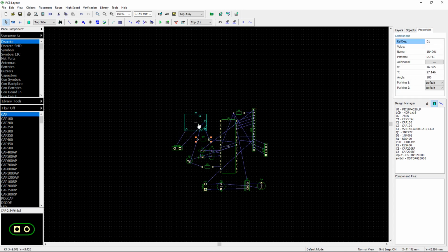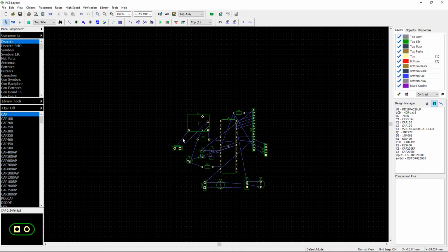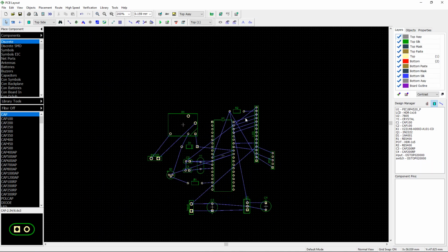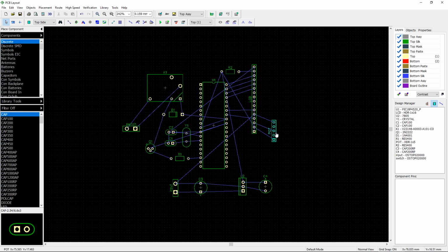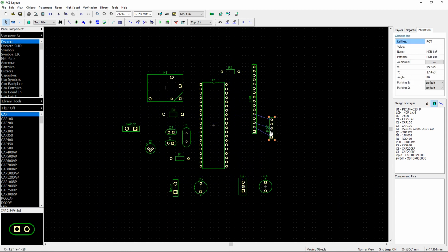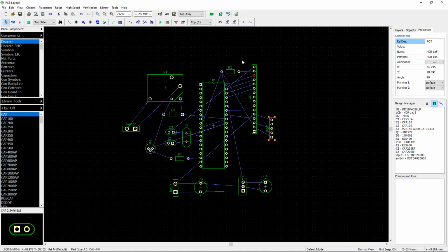Now I'm just refining things so that we have a very small PCB, and this can also be done after you have routed the PCB. But it's usually a good design principle to first of all arrange the components the way you want them to be. Then after routing, if you discover that you're having a lot of trouble in getting traces that are not intersecting, you just then space the components out.